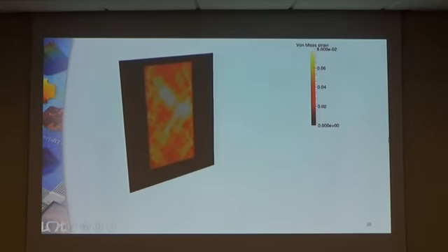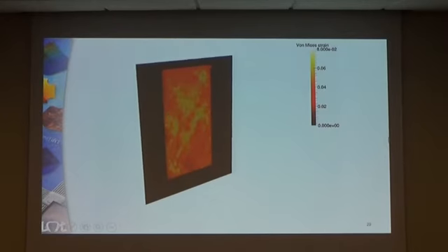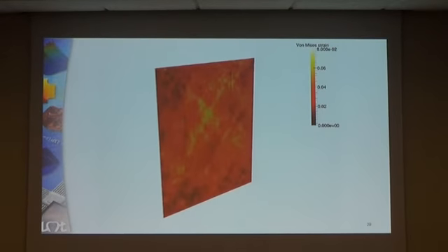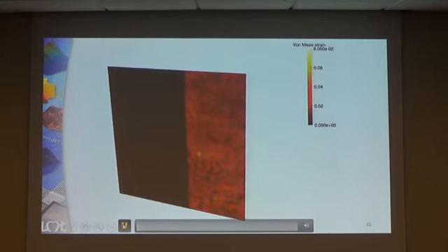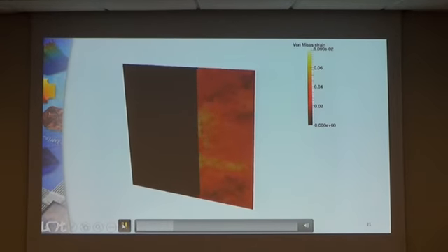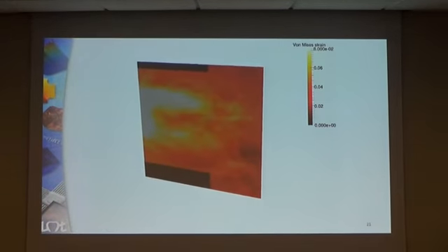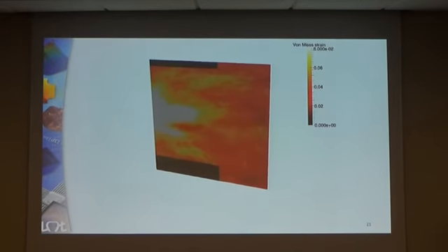Already very soon after the notch root, we have this onset of the strain bands, and this pattern is going to be simpler when we go to the slanted region, where only one X-shaped slanted band remains. Also, we can observe the same thing for the true thickness direction. We have this horizontal band, and we can observe this intense dynamic activity of the horizontal bands.